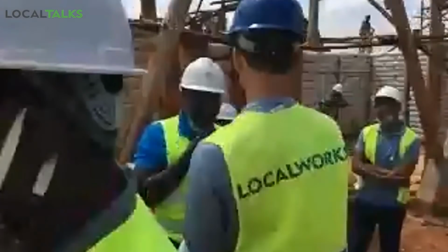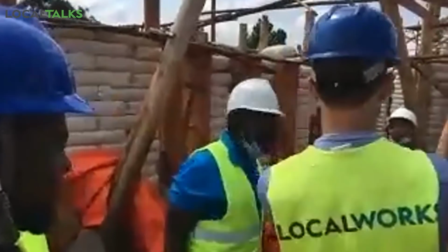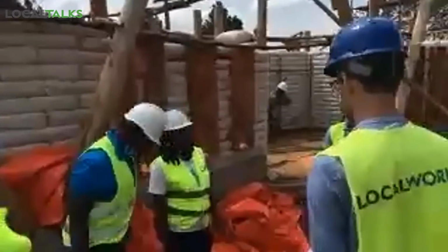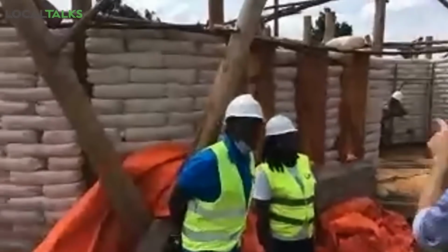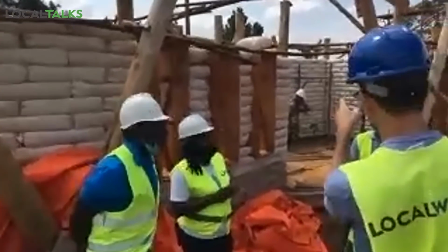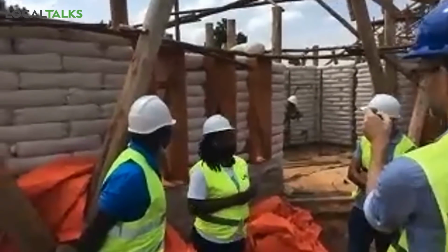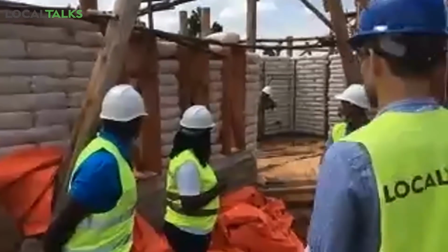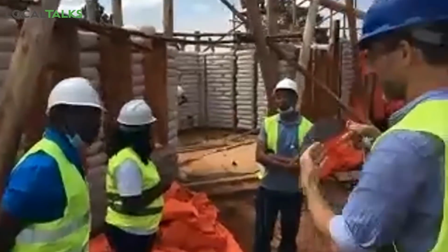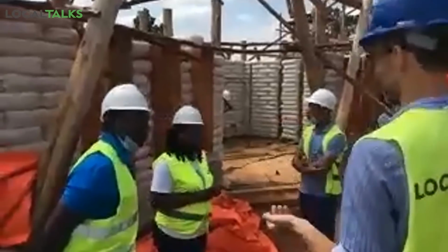Eucalyptus has a tendency to warp over time or to split up. You cater for that in the door and window frames. There's two answers to that. One is that we have really insisted on this wood being kiln dried. And the other one you can sort of see. These are actually very, very small members that are laminated together, glued together. In many ways, the smaller they are, and the better they are connected to each other in a staggered way, the better you address the problem of cracking and warping.